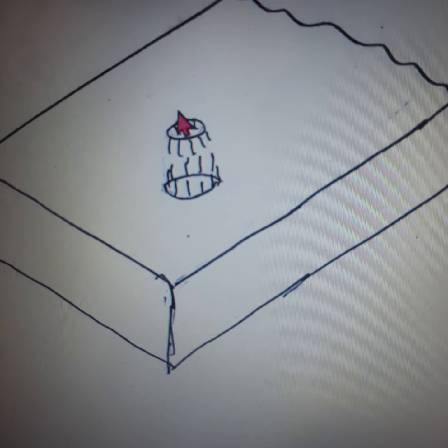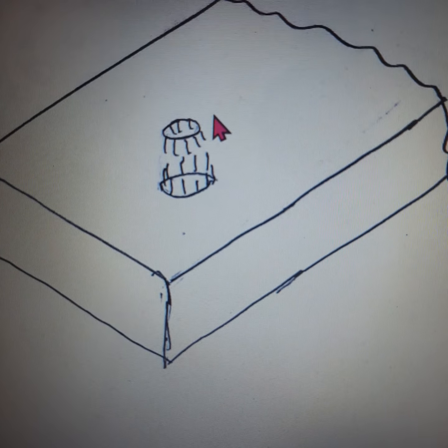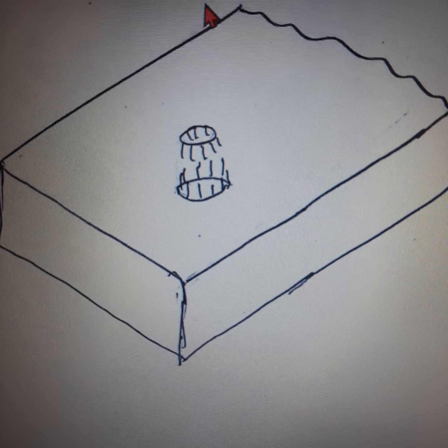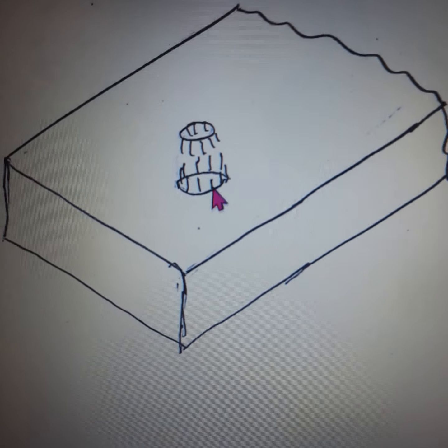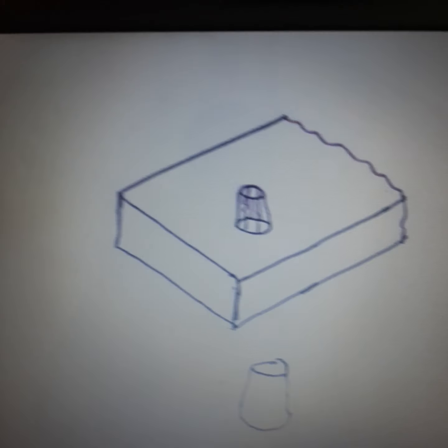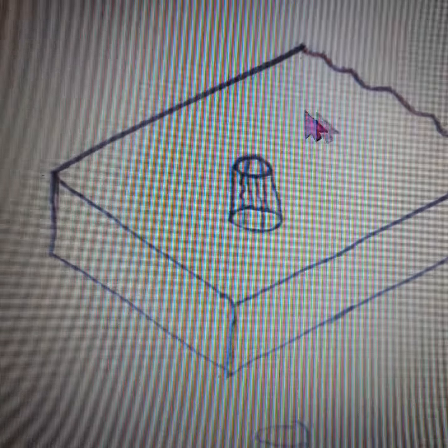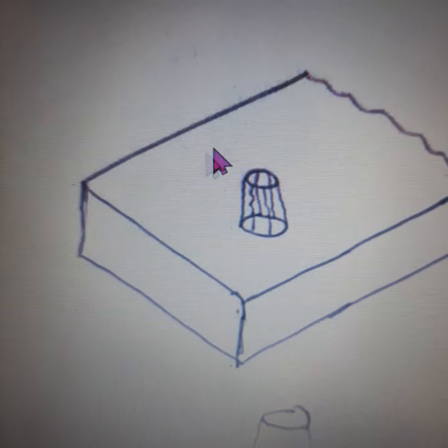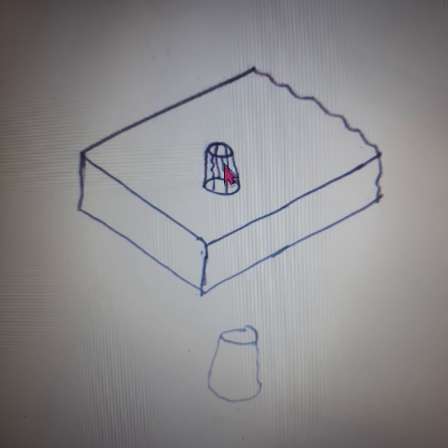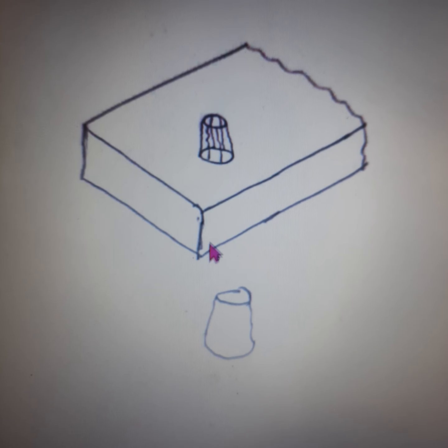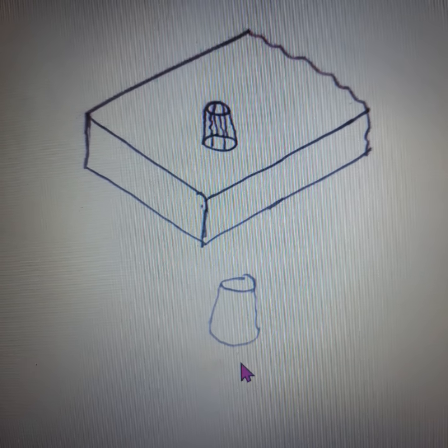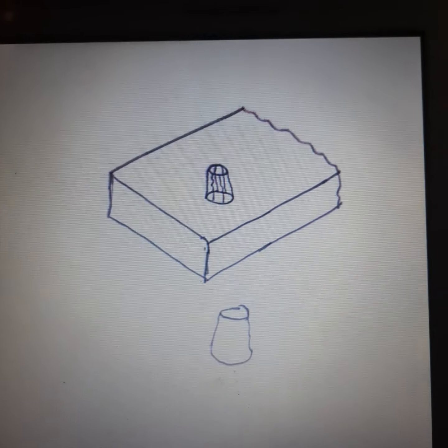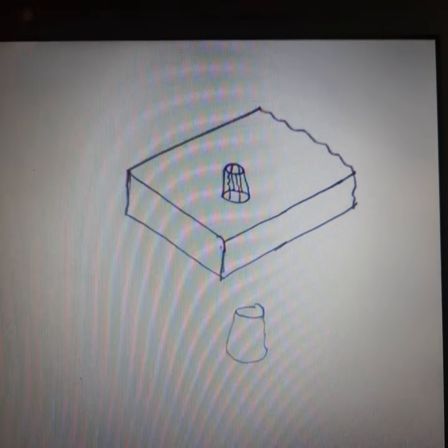The cracks start originating from both the top surface and bottom surface of the feed strip, as shown in this figure. Further downward movement of the punch will make the cracks join together like this. So the cracks originating from the top surface and the cracks originating from the bottom surface of the feed strip, both the cracks are joining together. At this stage, the piece is separated from the feed strip and it is falling through the opening on the die plate. So this is how the cutting action is taking place in a progressive press tool. So the cutting action is taking place due to shearing action.